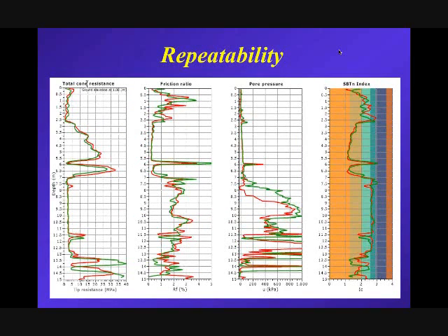This next slide is just to illustrate the repeatability of the test. This is two soundings, they're to 15 meters, and you can see excellent repeatability on the tip resistance, pretty good repeatability on the friction ratio.